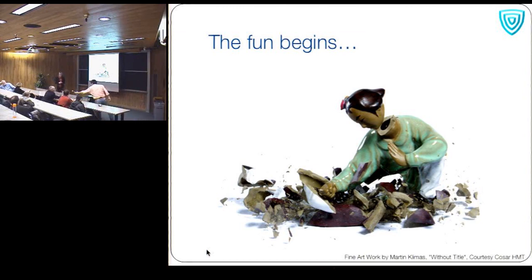Then how you had strength, of course, identified as this peak stress. So what are the conditions then for your cracks at that peak stress? Because all those conditions were always initial, correct? So when you identified a certain flaw density or porosity, that was initial. Yes. And so, but for each of those families, you have this crack growth that's continuing.